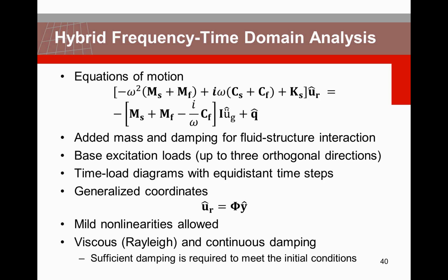Or if you only want to do a structural analysis, but want to use your mode shapes because you're mainly doing a nearly linear elastic kind of analysis, you can also use the hybrid frequency time domain method. Your pseudo force will then remain small, so you don't need many iterations, but you can still use the benefit of using these generalized coordinates, the mode shapes. So nonlinearity is allowed. You can use viscous and Rayleigh damping.